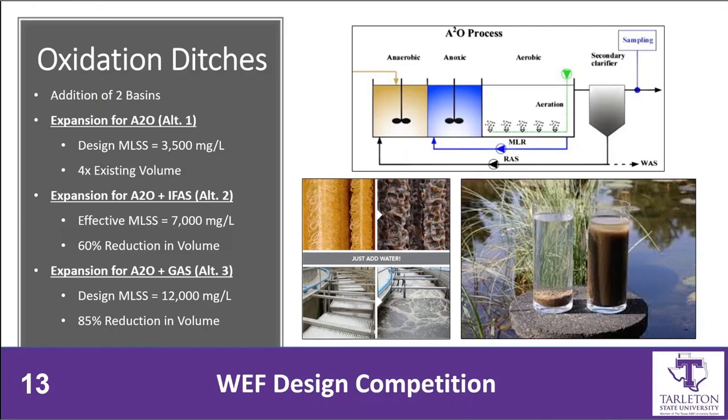Alternative 2 includes the same A2O process, but with the addition of an integrated fixed film activated sludge media, like that shown in the bottom left picture. This design allows the design MLSS to remain at 3,500 milligrams per liter, while increasing the effective MLSS to 7,000 milligrams per liter. This eliminates extra solids loading to the clarifiers and reduces the required volume evaluated in Alternative 1